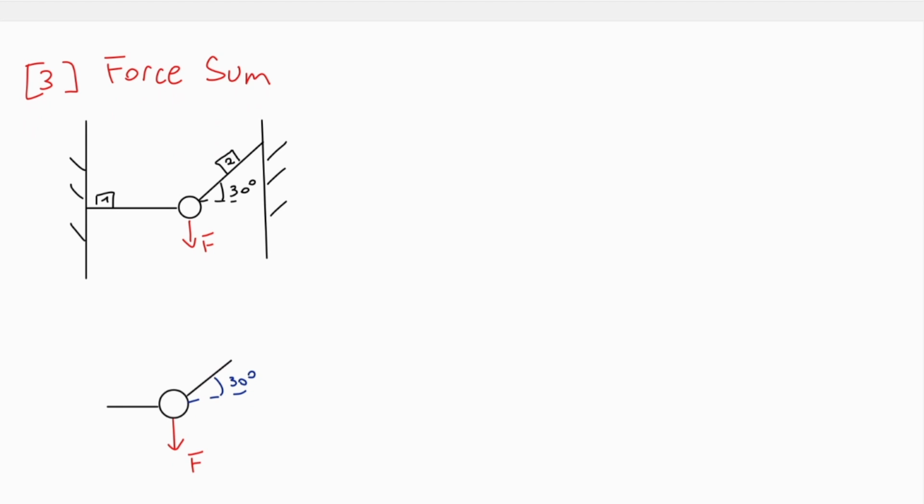And very importantly, for basically every mechanics course that I know about, you always define tension as positive and compression as negative. So here we will look at this sample question, which is a very, very simple case of how to do a force summation. The first thing I have to do is take a free cut because I'm trying to figure out the truss forces 1 and 2.